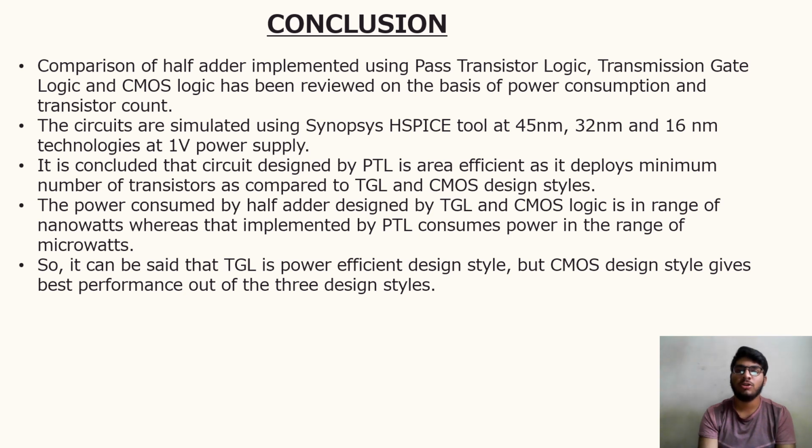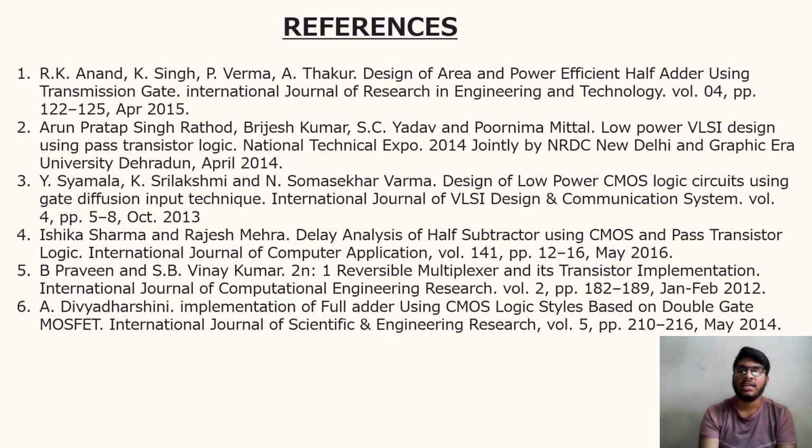The power consumed by the half adder designed by TGL and CMOS logic is in the range of nanowatts, whereas that implemented by PTL consumes power in the range of microwatts. So it can be said that TGL is a power efficient design style, but the CMOS design style gives the best performance out of the three design styles. The next is the references of the research papers.